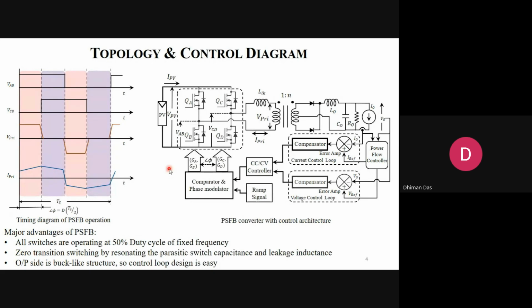When you do this, all the ringing effect or the parasitic effect will die out because you are charging the body capacitance and parasitic inductance. So you can eliminate the switching loss, and your efficiency will rise up. And there is no extra capacitor; we are using the parasitic components of the system, and we are achieving more efficiency with that. That is the beauty of this converter.